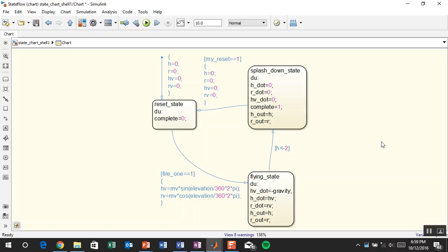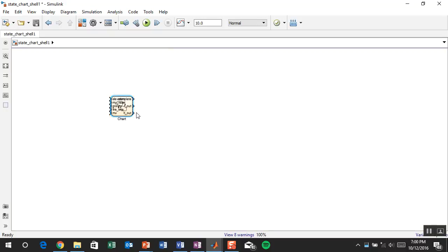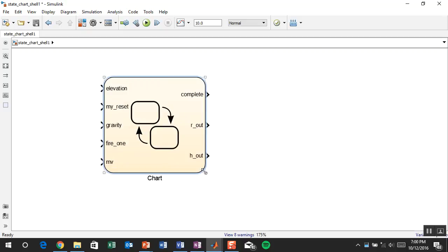So even though we've already solved the problem, we're remodeling it in a way that's more computationally efficient. So this is going to be able to use variable step solvers and zero crossing detection, and then we don't have to track the shell every foot. It can go 1,000 feet between those solve steps.